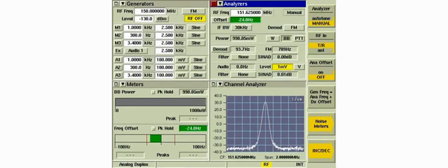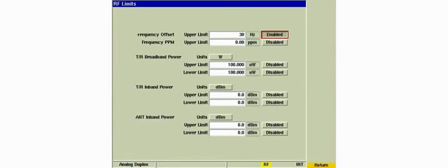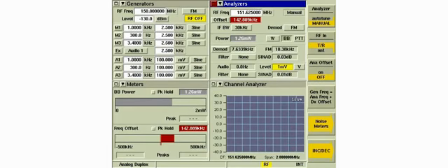Note that the frequency offset meter is displayed in green. Green indicates that the reading has not exceeded the limit of 30 Hz. Now let's assume the radio has a tighter specification of 18 Hz frequency offset. Now, when the radio is keyed, the frequency offset is displayed as red. We know immediately that 24 Hz frequency offset exceeds the 18 Hz specification of the test.